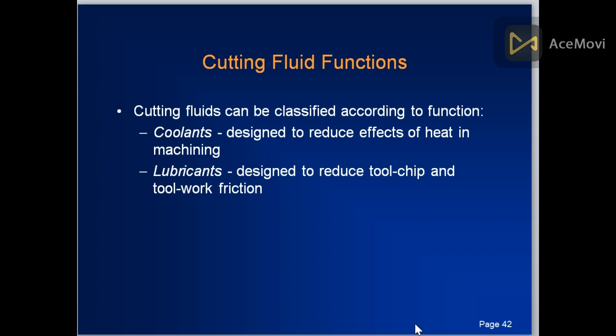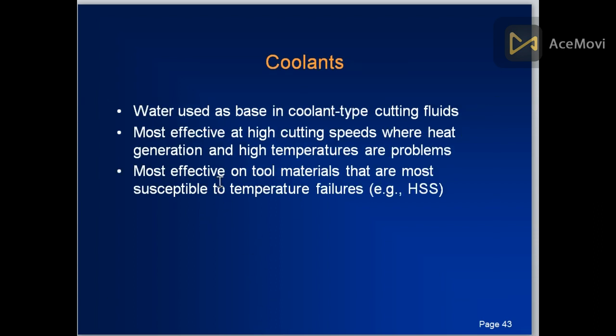Cutting fluid functions can be classified according to function. Number one is coolants. These are designed to reduce the effect of heat in machining, while lubricants are designed to reduce tool-chip and tool-work friction.